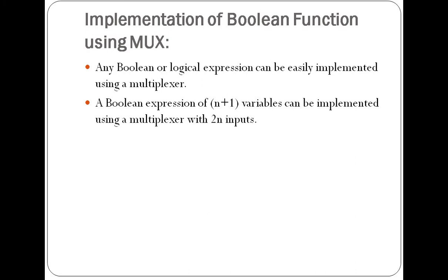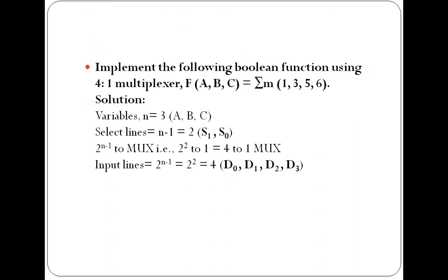We can see the implementation of a Boolean function using a mux or a multiplexer. Any Boolean or logic expression can be implemented by using a mux. A Boolean expression of n plus 1 variables can be implemented using a mux with 2^n inputs. We can see one problem.